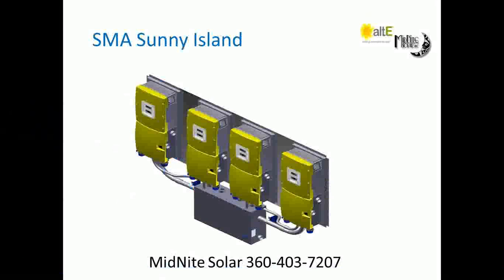And then we have a slave E-panel, which would be used in any system that has more than 1 Sunny Island. So if you've got a quad like this one, you'd order a quad master and 3 slaves. Something I've seen a couple people do already is, remember we talked about the battery combiner box and the fact that it can hold battery breakers. I've seen people use the battery combiner box to replace the 3 slave E-panels. They put their battery breakers down here for the 3 slaves, and then they pipe right into the 3 E-panels from the battery combiner and pull their AC wiring right through there as well, saving themselves a few coins on the E-panels if they don't feel the need for that extra.